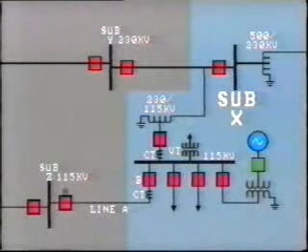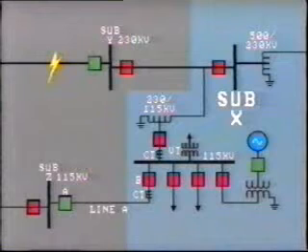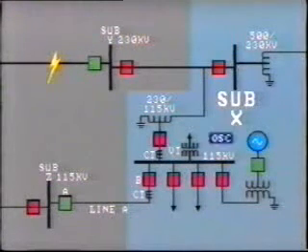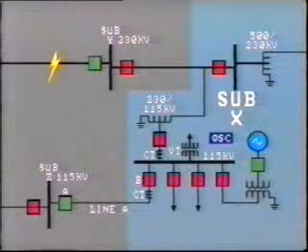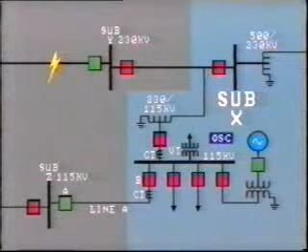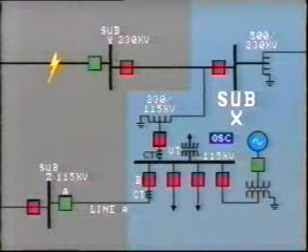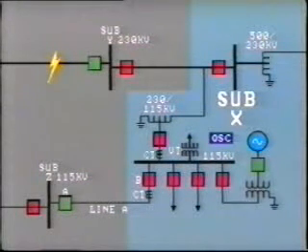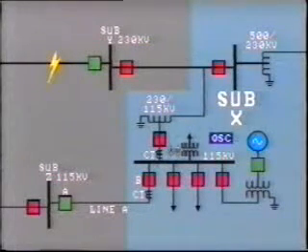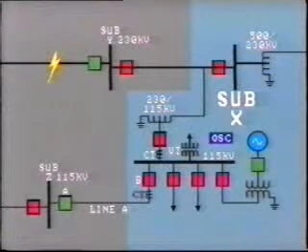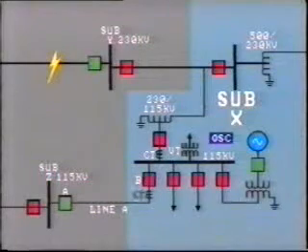Breaker A at 115 kV substation Z trips for a remote fault on the 230 kV system. With the help of the oscillographs located in substation X, we were able to spot the problem and correct it. In substation X, the oscillograms monitor the transformer breaker's A phase current and the 0 sequence residual current. Also monitored are the 115 kV bus voltages in all 3 phases, as well as A phase and residual current for breaker B connecting to substation Z.